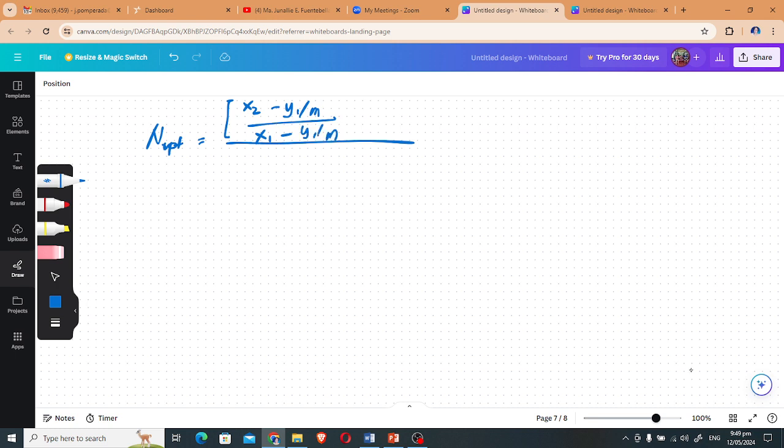You multiply it with 1 minus a plus a. So this is your numerator, the entire numerator over ln of 1 over a. And this is your stripping factor. The opposite of the gas absorption factor is the stripping factor.